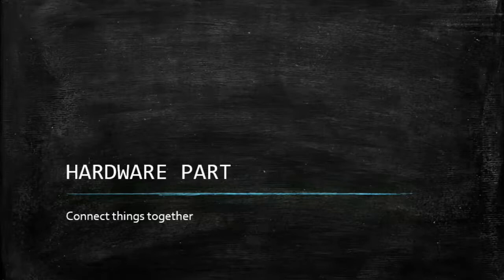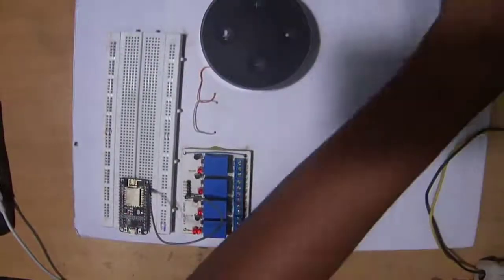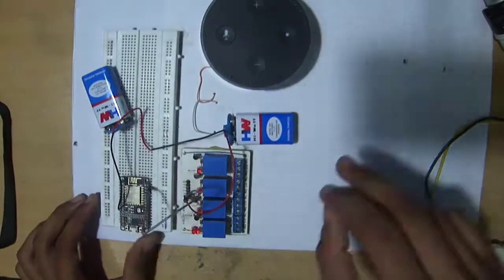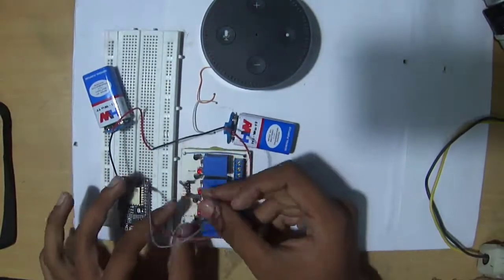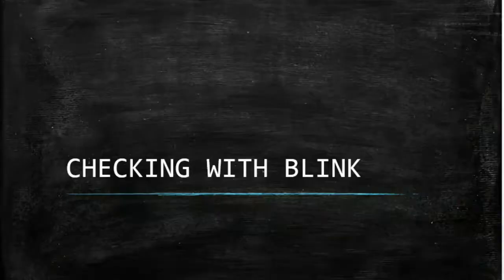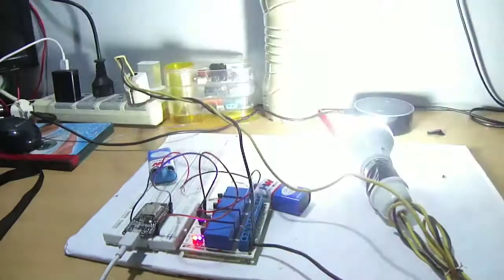Let's see the hardware part of this project. The hardware part starts from placing the Wi-Fi board on the breadboard and connecting it with the relay. In my case, I use a 12 volt relay, so I have to give an external power supply for it. I have connected two 9 volt batteries in series to make it 12 volt, and then I connected the bulb with it. Update the code to it. Check. We are going to check it with Blynk.